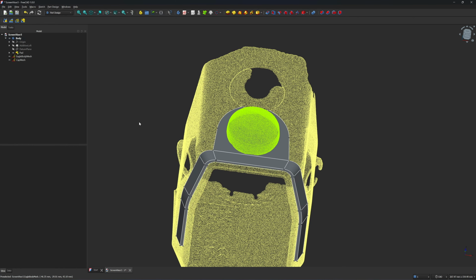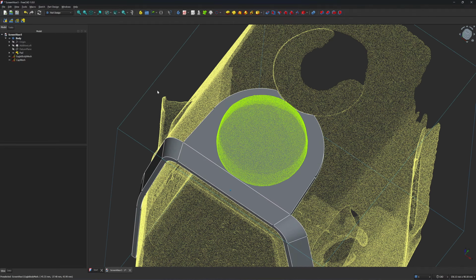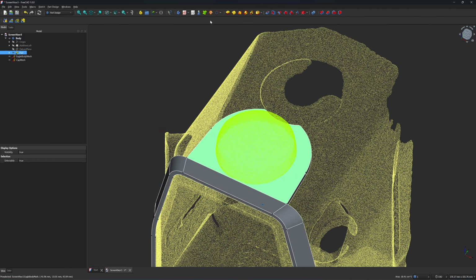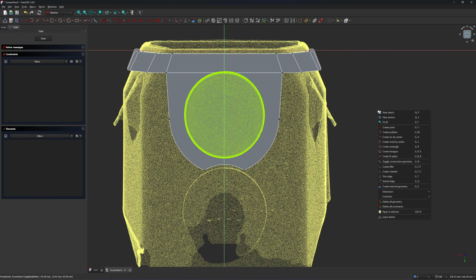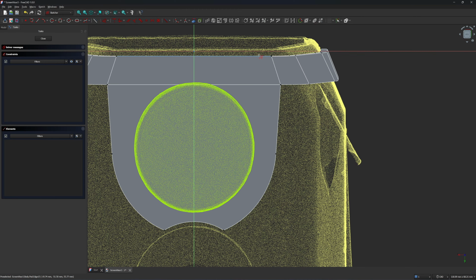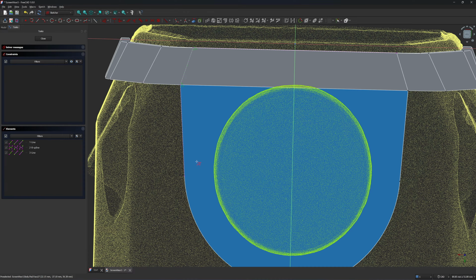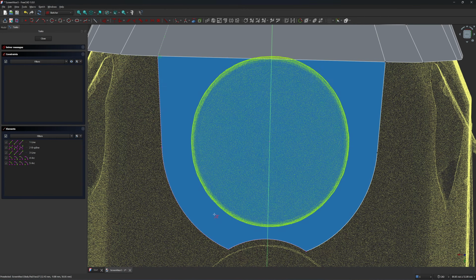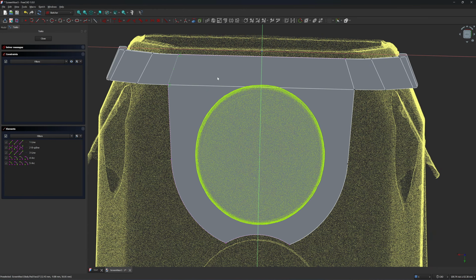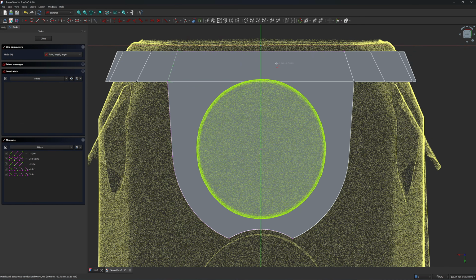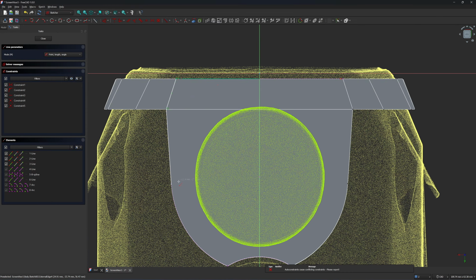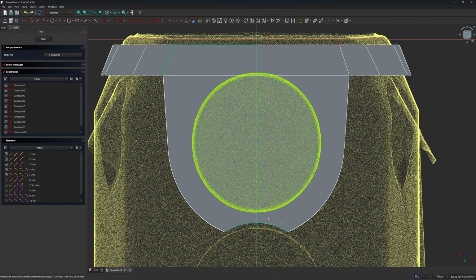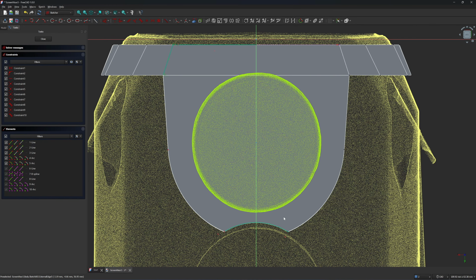Okay, next I'm going to create a stiffener of 3 millimeter. I click on this plane, and then I'm going to create a sketch, and then I'm going to project the lines. 1, 2, 3, 4, 5. So I project 5 lines. Trace the lines. Click on lines. 1, 2, it's not connected. 2, 3, 4, 5. Okay, we have 5 lines.